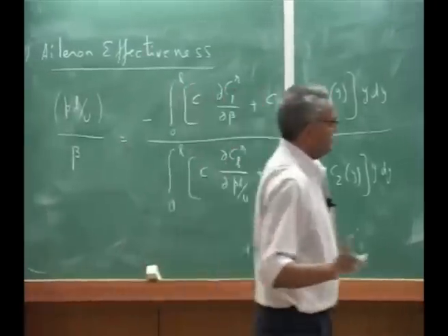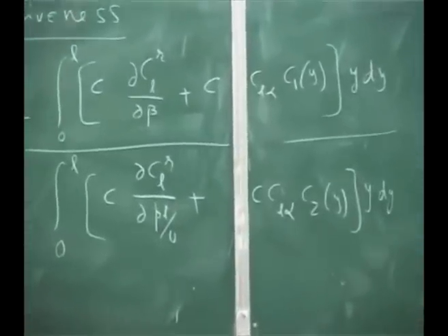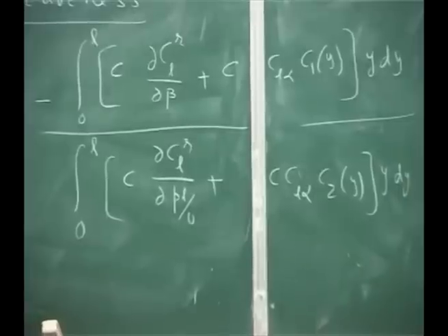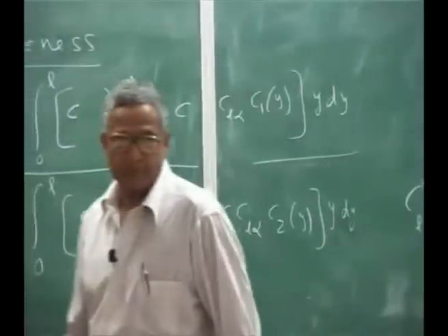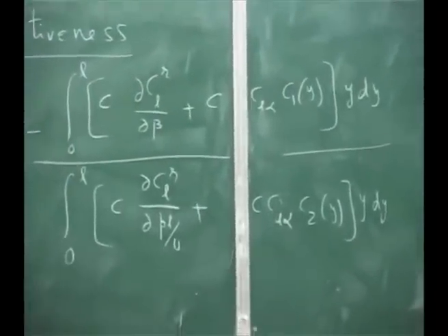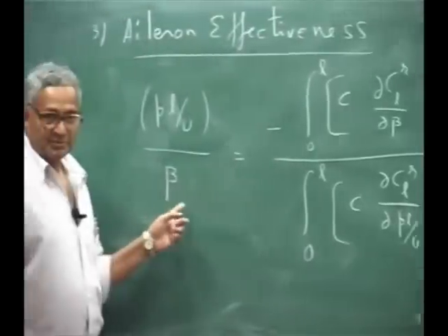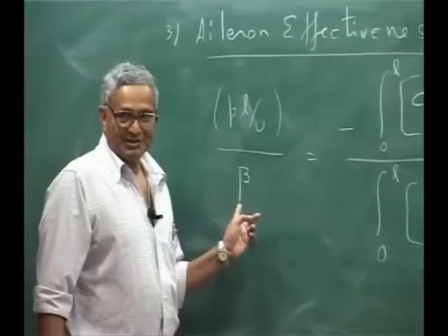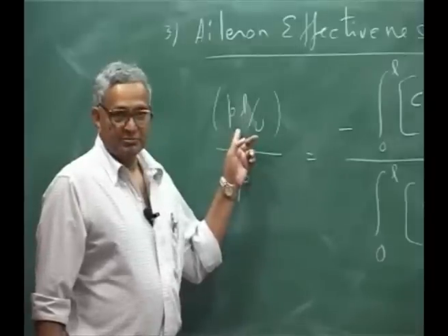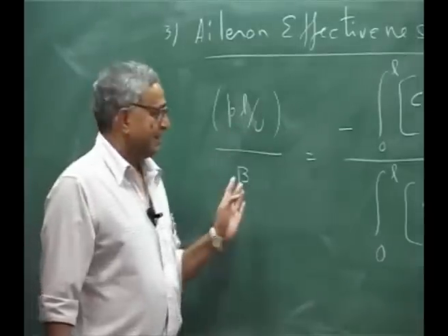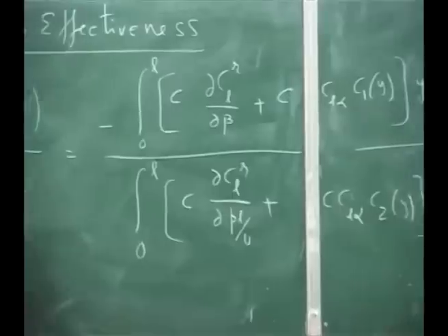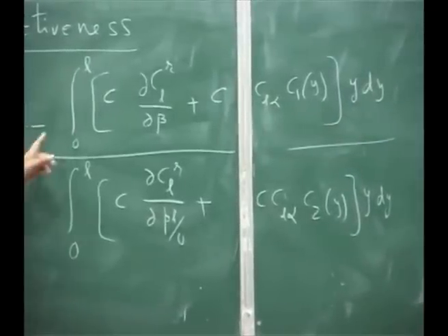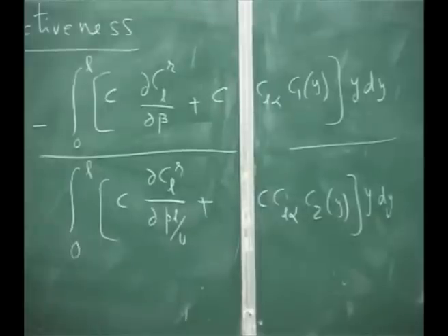Wait, one minute, I'm just checking. This is a lift coefficient, right? CLR. Okay, C into lift coefficient. I'm taking q c CL. Now you see here, any deflection of this, if this is 0, that means I don't get any roll rate, which means the aileron is ineffective. So the speed at which the numerator becomes 0 is my aileron reversal speed.